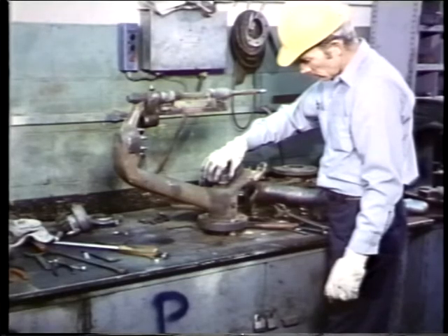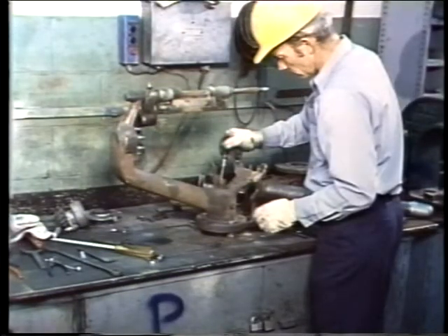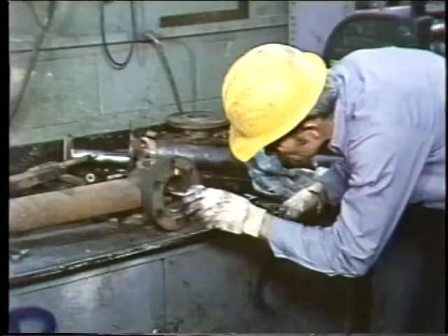All the old valve packing can be removed, since in this case it wasn't necessary to remove it earlier to pull the disc and stem. When the packing is out, the condition of the guide can be determined. The stem should show no sign of free play in the guide. It should move freely in and out, and it shouldn't bind.